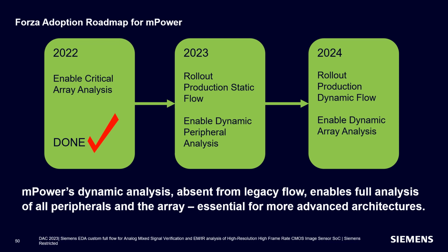The next step for us is to go one step further and take advantage of the AFS integration of mPower to perform dynamic IR drop analysis on the peripheral circuits. This is something we cannot do with our legacy flow, and we are very excited about it.